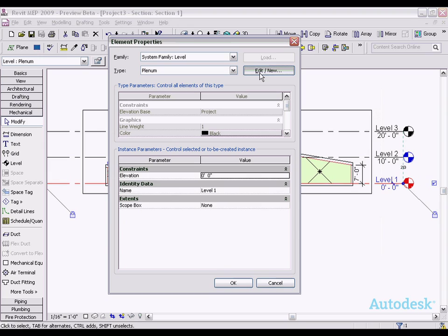So what's happening is there's a calculation height, and that's being calculated by the system. And at that calculation height we're pushing outwards until we find bounding elements. And that's what's defining the cross-sectional area. So we can go ahead and illustrate what that really means if we modify this particular level type to no longer use the automatic computation height, and let's go ahead and set this to something like 4 feet.